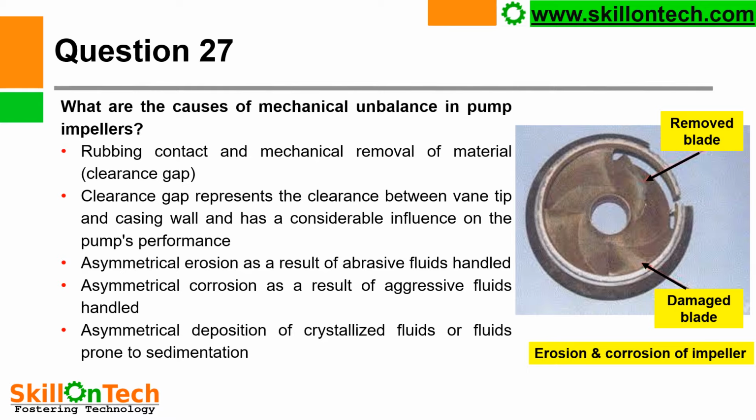Clearance gap represents the clearance between vane tip and casing wall and has a considerable influence on the pump performance. If the impeller wearing ring clearances increase, there will be a loss of fluid because fluid will go back to the suction and it will reduce the performance of the pump.